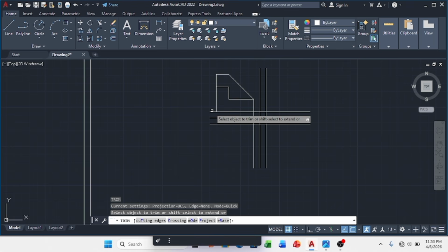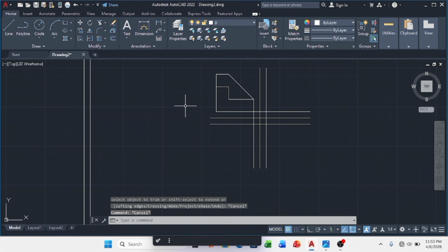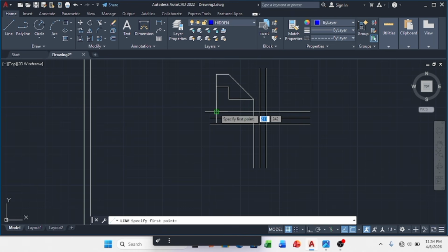So we come to the top here and choose header. Then we choose line. Then we project all the line downwards. So this is what we are going to use to draw the top view. If you recently use a command and you want to use that same command again, you can press enter so that you can reuse that same command.